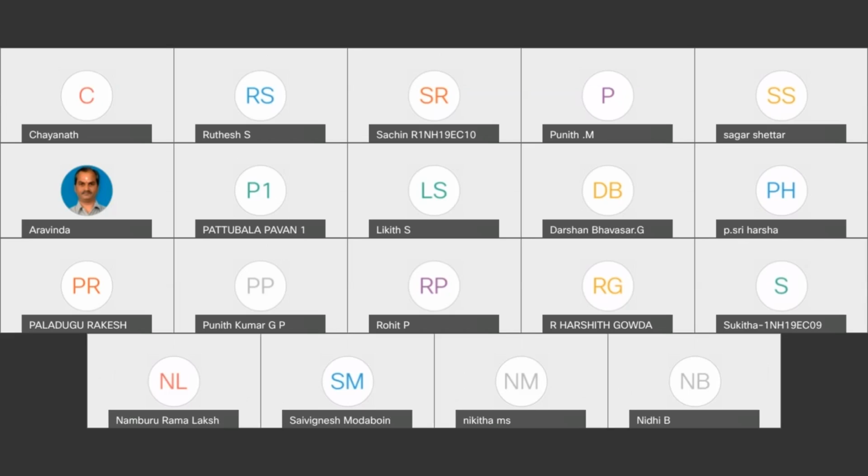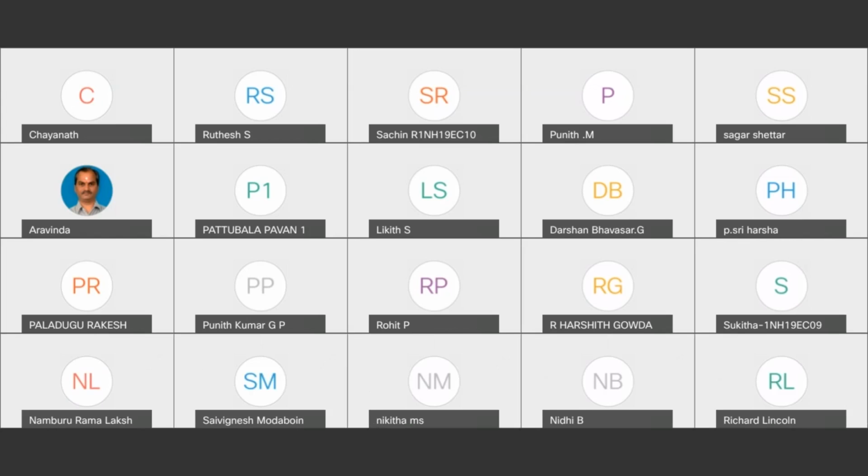Again, in digital designs, synthesis will happen there also, but that synthesis tool is much more brilliant than the present synthesis tool. There is a synthesis tool in Cadence which is much more refined than the synthesis tool of FPGA. FPGA uses LUTs and multiplexers, whereas Cadence synthesizer directly uses the primitive library elements, including logic gates, which are present in the Cadence library. You will learn more about it only in next semester. So as of now, understand that we are not worried about the physical size of the circuit here, because we have already paid for the chip. That's all. I hope the answer is clear to you.